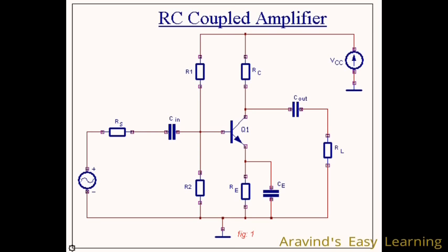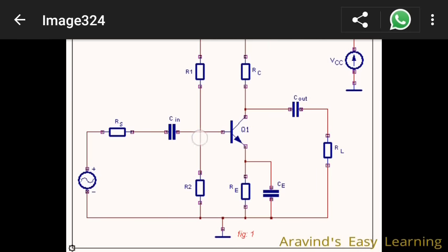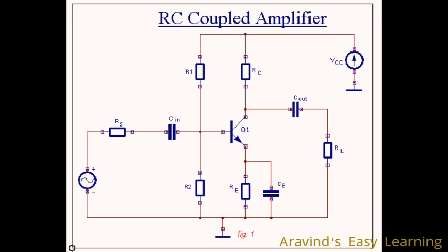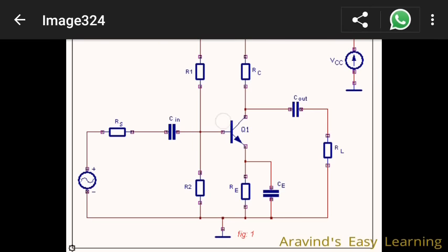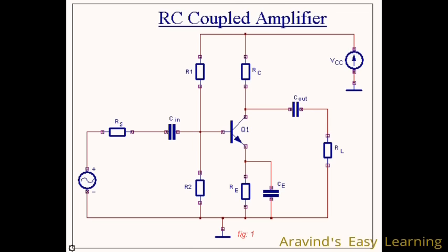See, we are using common emitter configuration. In a common emitter configuration, the output is out of phase with the input. As a result, a 180-degree phase shifted output is fed back to the input. And thus, the output actually produces negative feedback on the input, and thus the gain is reduced. Sounds interesting? Okay, so that's about the inter-electrode capacitance.